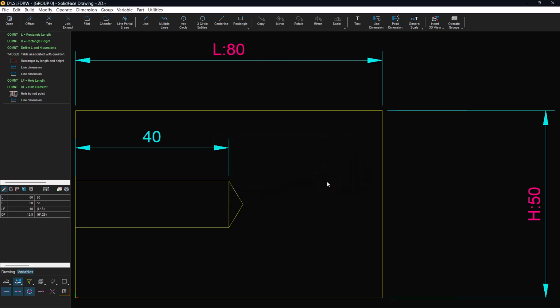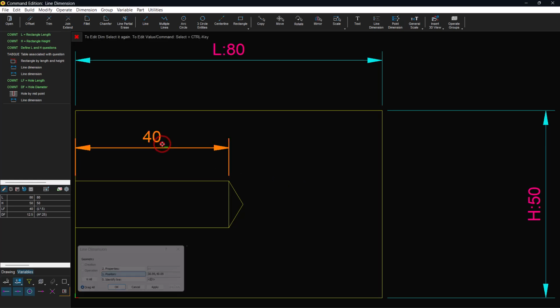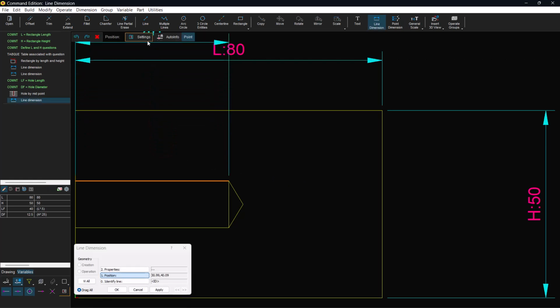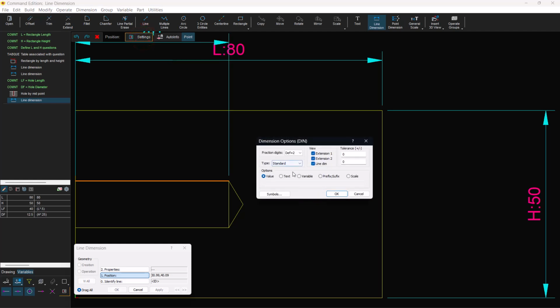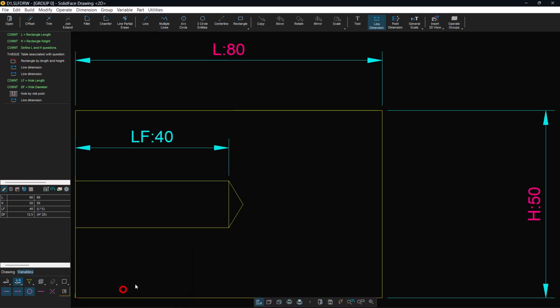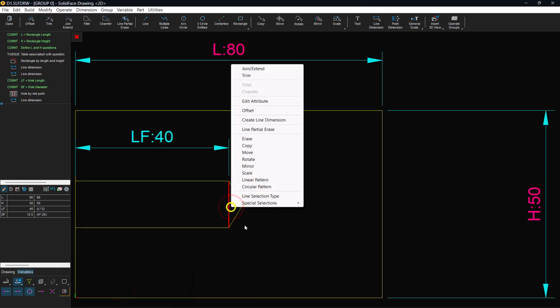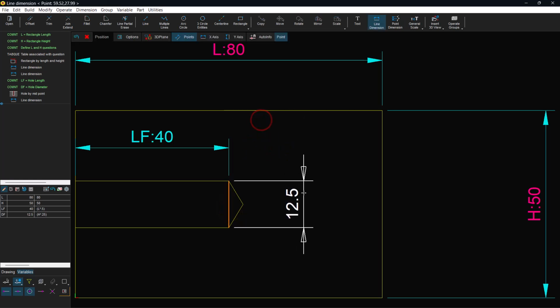How do I use standard dimensions to indicate which value displayed in the dimension text is associated with a variable? Correcting the dimension of the whole length. In the Settings and Variable option, indicate the LF variable associated with this dimension. See that now when creating the whole diameter dimension, I already informed that the DF variable is associated with this dimension.